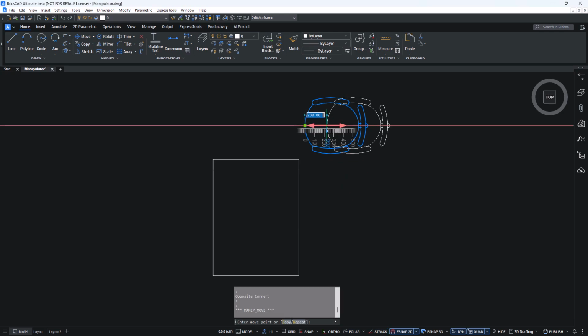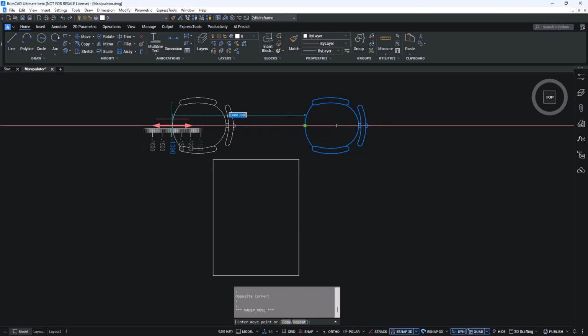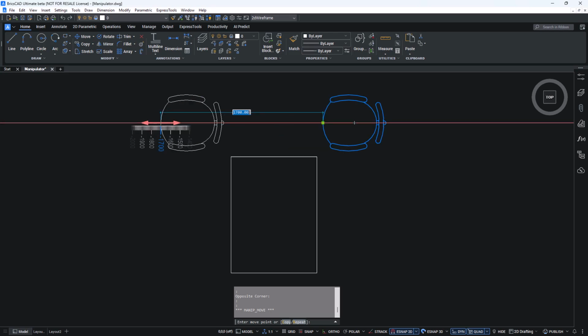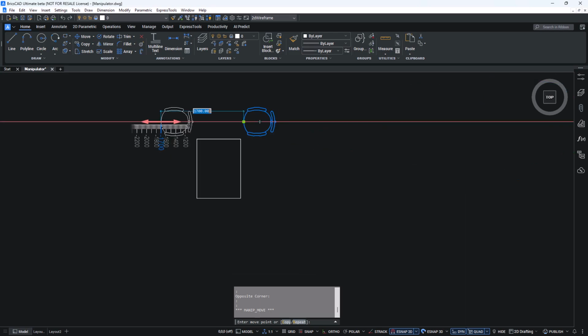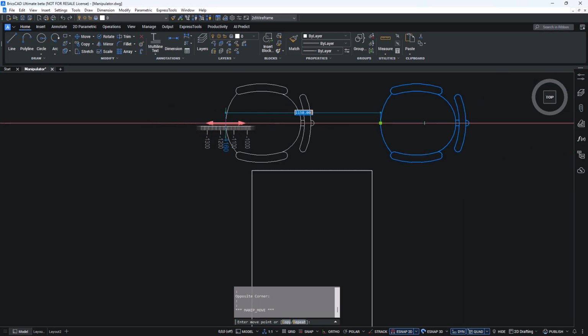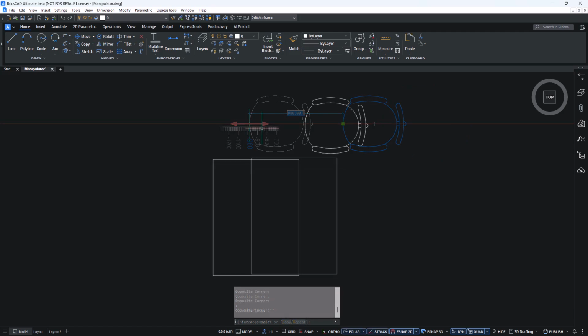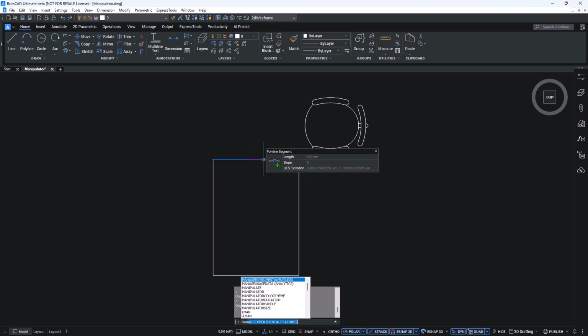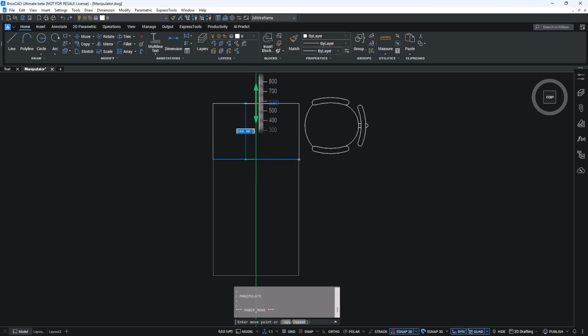Left-click on one of the directional lines to move along that axis. You'll then see a ruler is displayed, and the ruler's increments adapt to the zoom level. You can also select subentities separately by using the Control key. For example, we could extend the length of this table by selecting a single line.